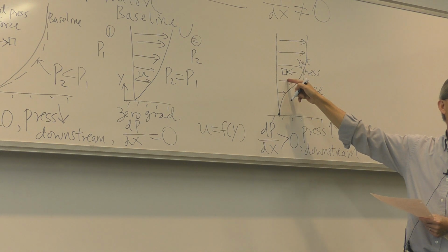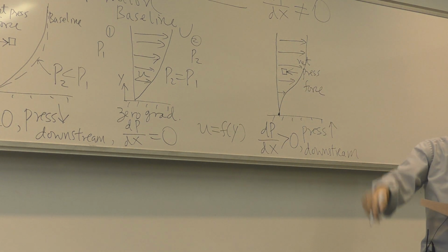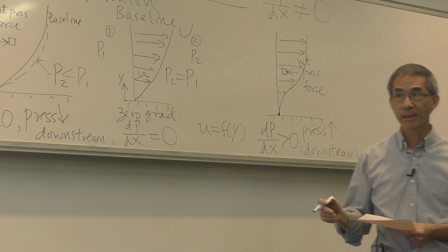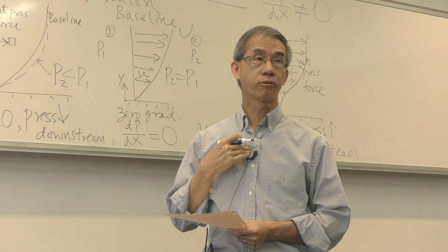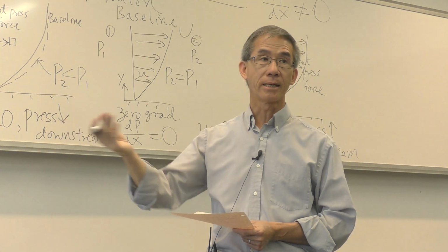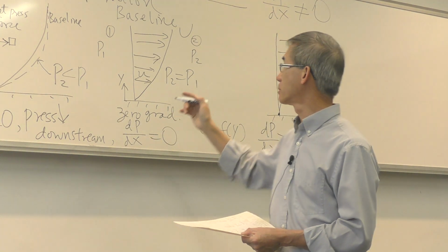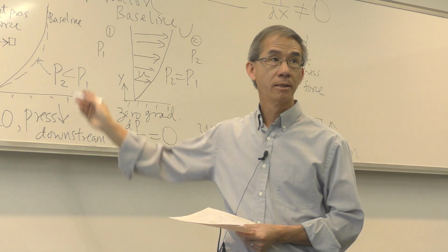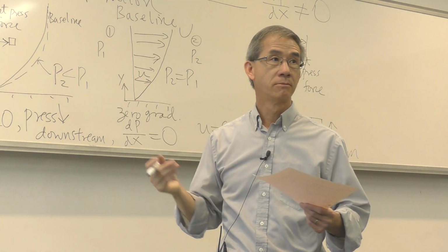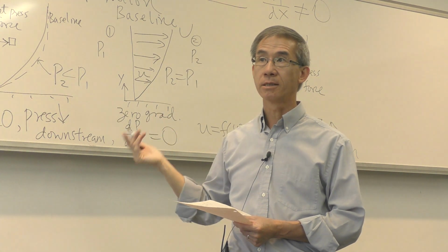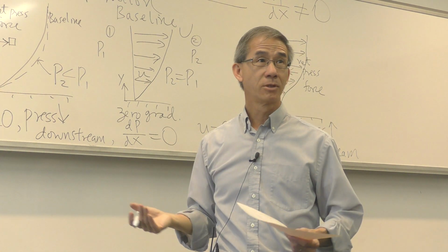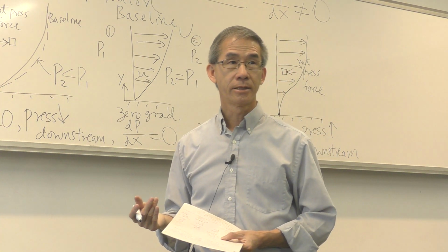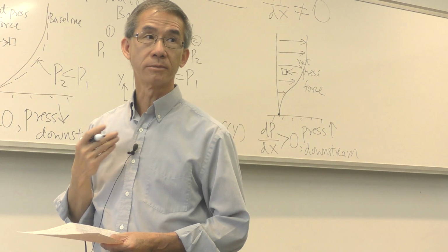It tried to slow me down. It will be me marching towards that wall. Every step I take, I have more and more resistance due to the pressure increasing downstream. And remember, in the boundary layer, I'm already tired. In the free stream, it may be 100 feet per second, but in the boundary layer near the wall, I have zero momentum. Close to the wall, I'm tired, 10 feet per second. I take one more step, there's more pressure pushing me.